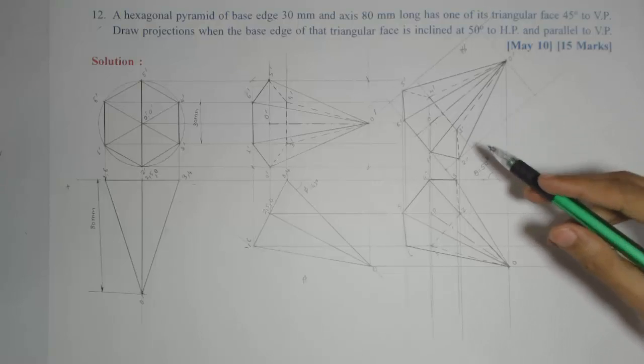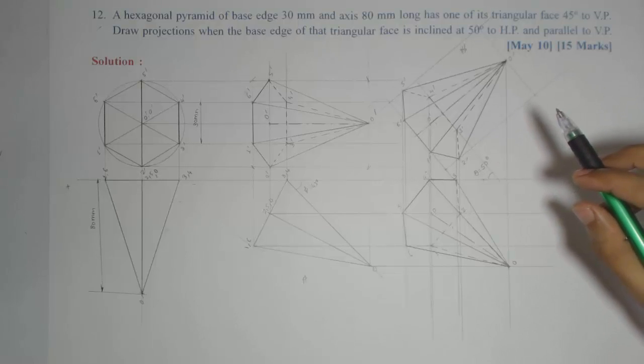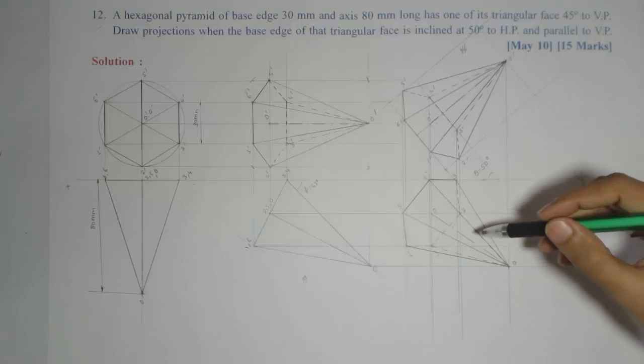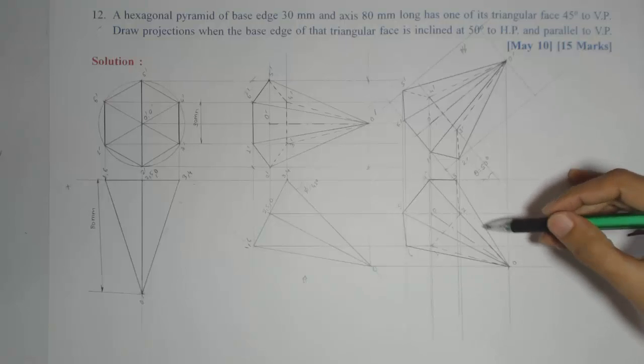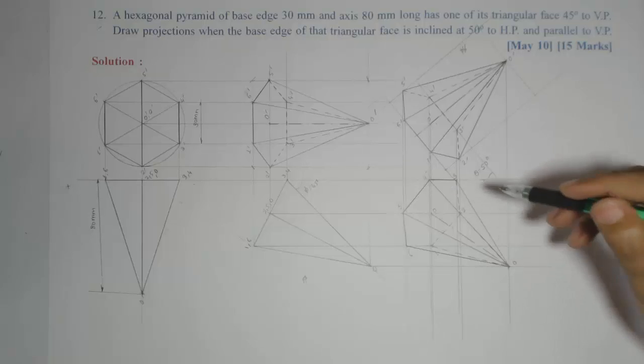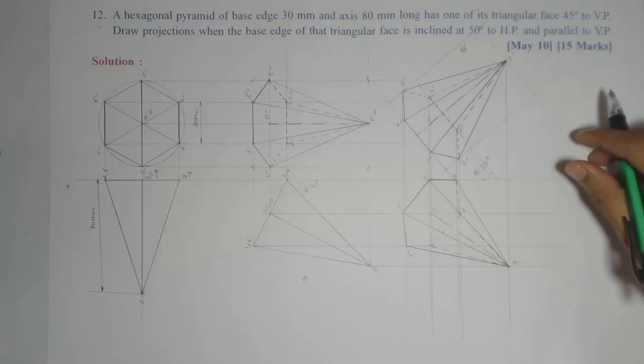If you want, you can check once again whether all lines or edges are drawn, nothing is missing. Okay. Here one thing is happening, that O2 dotted line is coinciding with O4 dark line. So we have shown dark line. So this completes the solution.